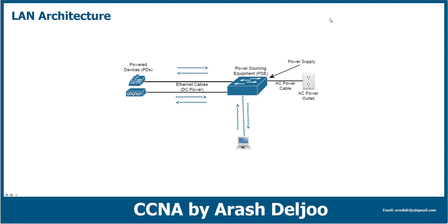This is the electrical communication, but we should know that by default the switch doesn't apply power to the other side. First, the switch should negotiate with one method, the method is not important, with the other side. If the switch determines that the other side is a powered device, it can apply the power.